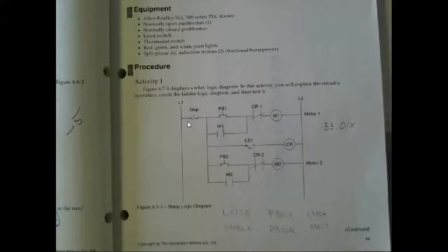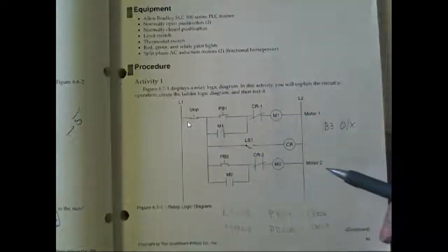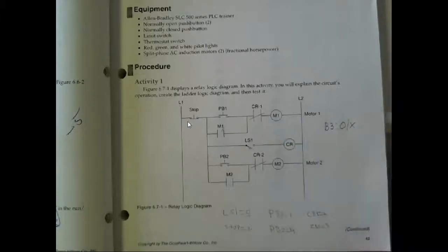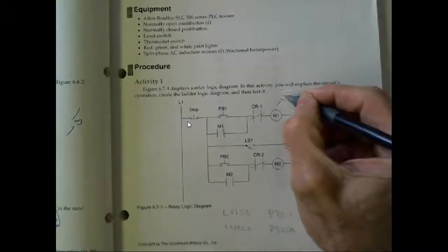And so do you figure out how to do this with the PLC box? If you go to the stop switch, you turn it down. You go to LS1. If that's open, are you saying that kills power on this one? No, if it's closed. Don't kill the power on everything. It drops the main contact. When you say kills power on everything, huh? They quit running. Yeah, the motors will. Yeah, if it hits this limit switch, both motors will cut off. That's right. Which here, of course, we don't have motors. What are we going to use? Whatever that is.